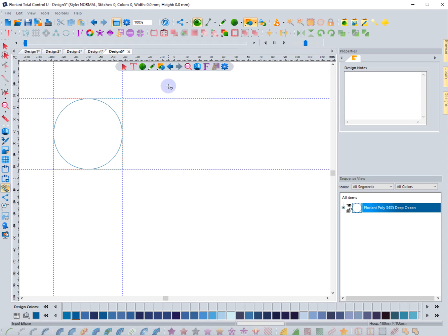So it's the same thing, or very similar to snap to grid. However, with the snap to guidelines, you control exactly where those lines are. And so sometimes that can be difficult with snap to grid. Sometimes they're not in the perfect shape that you need. So it's easy just to use the snap to guidelines to create the shapes as well.